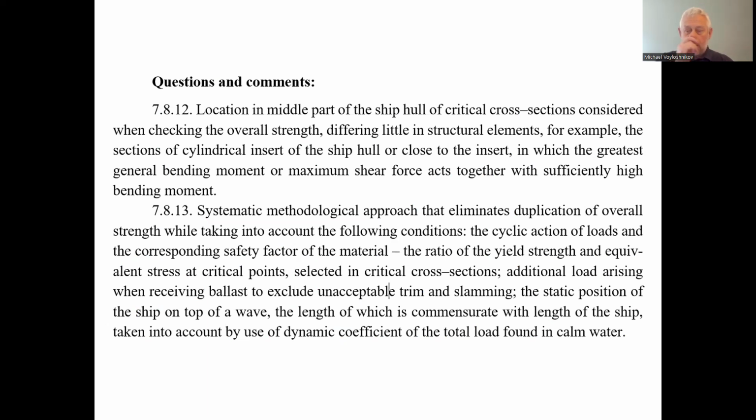So after finding the diagrams of the general bending moment and the shearing forces acting on the ship hull, the next issue is to indicate the critical transverse sections of the ship. These could be all the sections with a maximal bending moment or maximal shearing forces, or with significant shearing forces or bending moment if they are together in one or a few transverse sections. This could be the critical transverse section subject to the next check of the ship's general strength.